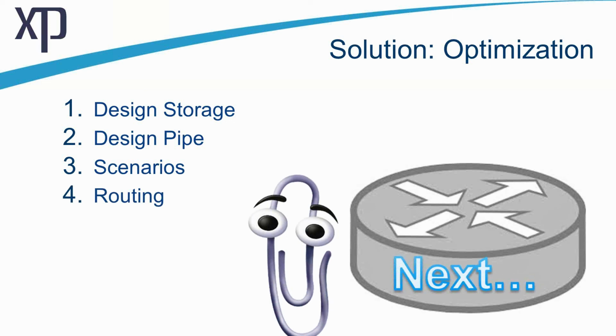Well, that's obviously the best increase in efficiency, if that wet well can be tied to the gravity line and the lift station itself can be removed. That's a great routing example because that will change how the flow moves through the system and change the impacts of the system. So that's a great scenario to compare and a really good use of a model. So that's a quick overview of optimization.